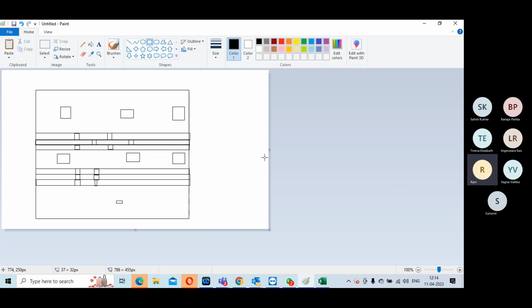Okay, because there are 2-3 scenarios I will tell you. Be very clear. The fly line connectivity may not have happened just because of the RTL. RTL has given, but DFT would have screwed up. I will tell you how. When they are adding MBIST, they are combining this memory and that memory. So the BIST connectivity is what creates your fly line logic. The tool won't understand. So if you allow the tool, it gets screwed up, and that is why it sits over here. You have to say, no, this module is supposed to be here. You have to create a separate MBIST group for this.